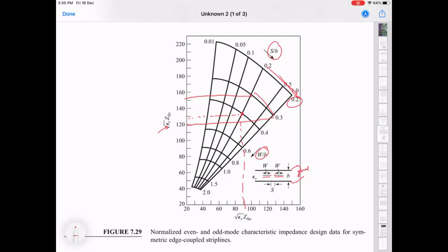Sorry. Look, this direction is increasing gap. So we are talking about bringing them together, which is the opposite direction. And there the even mode impedance actually goes up as you bring them together. Okay. We can actually see this when we open up the model and see, but I think it's the opposite argument that when you bring them together, there's some capacitance now between these two.